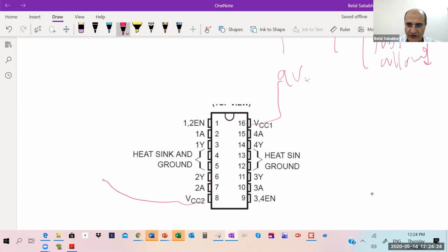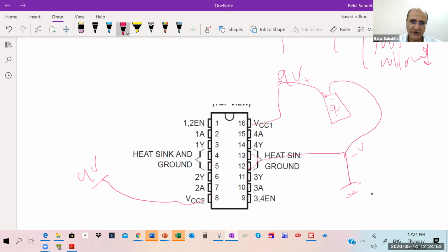And this is the same for the other motor because these are 2 H bridges, 9-volt battery. The ground, these 2 lines will go to ground, which is the negative side of the 9-volt battery. The positive side will connect here, negative side will connect here, and another one for the other side. It also would connect to the microcontroller ground, so the grounds will need to connect to each other.